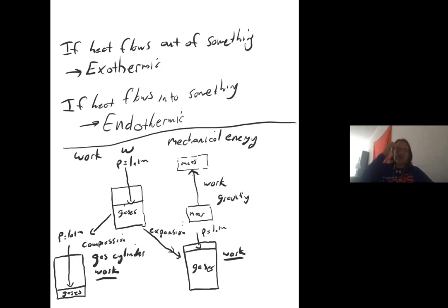The only difference between those two is the sign, okay? So by our convention, we have a convention for this. Here, we would say the work is negative. Here, we would say the work is positive, okay? So compressing a gas, pushing it to where it's got a smaller volume, that adds energy to the gases. And so it's a positive change. When gases push the atmosphere away or they push some device away, that's a negative change. So work in that case is negative, okay? So we have a sign, that's called a sign convention, okay? And we also have a sign convention for heat. So what I'm gonna do is I'm gonna make a little table.